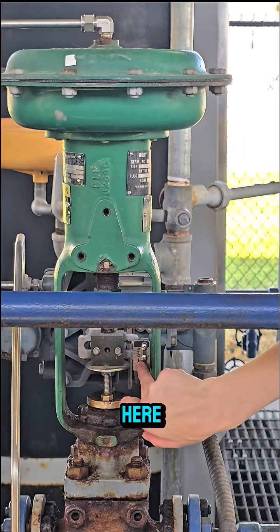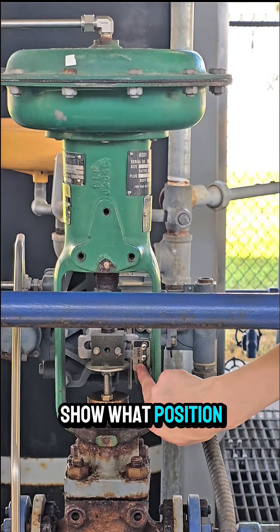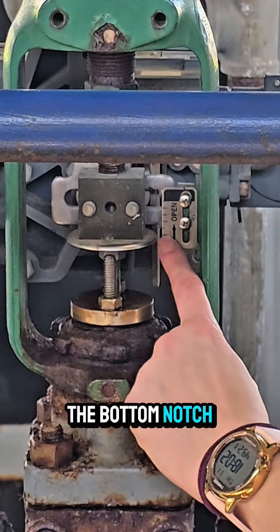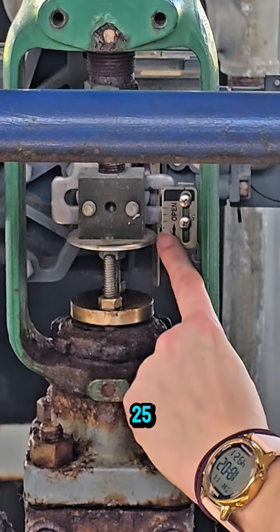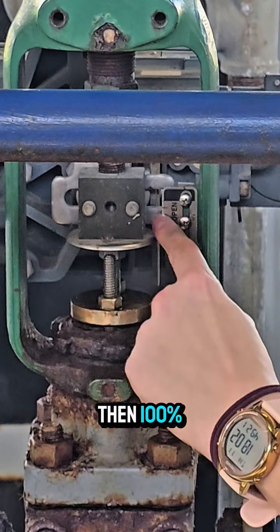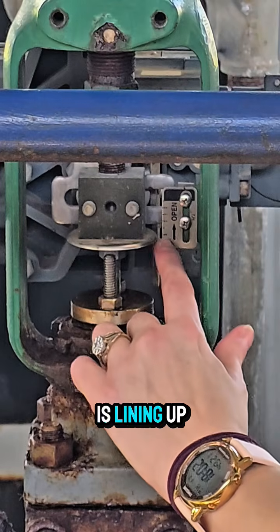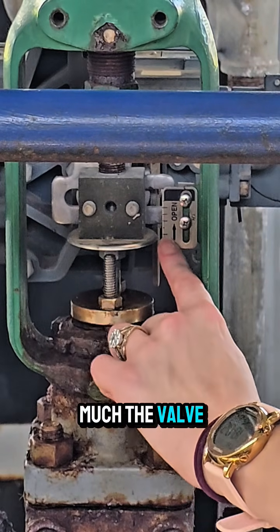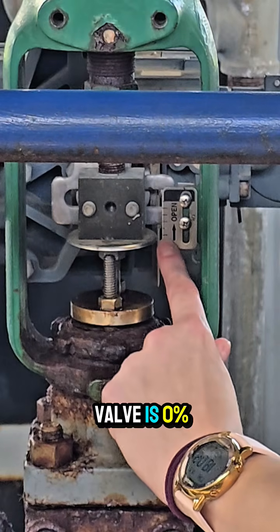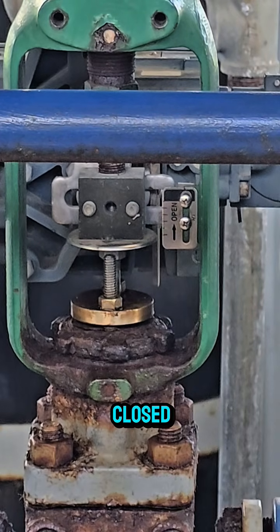This indicator right here is used to show what position the valve is in, what percent open it is. The bottom notch is 0%, then 25, then 50, then 75, then 100%. Whatever that disc is lining up with is how much the valve is open. Right now, the position of this valve is 0% open, so it's fully closed.